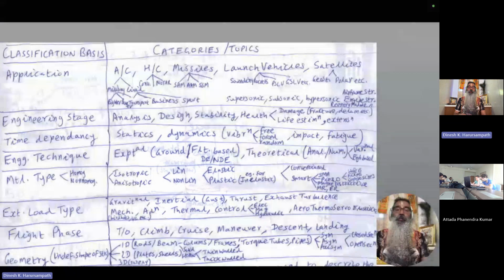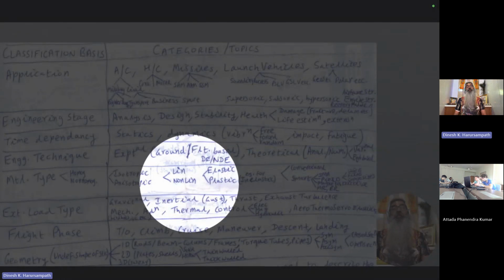The next thing in terms of the material, the way we analyze a structure is through linear material models or non-linear material models. For most part, the loads are very, very small, so you will end up with smaller strains. And if the strains are small, you will end up with a linear model being good enough. But if the load reaches such a level or the structures are so thinly made that they are not able to handle the load, then the strains can become very large. And when the strains become large, the stress-strain behavior becomes nonlinear. So in other words, if I plot the stress versus the strain, if it's a straight line, it's linear, and that is valid for very small values of strain. But as you go for larger and larger strains, the stress-strain curve can become nonlinear, especially for ductile materials like metals.